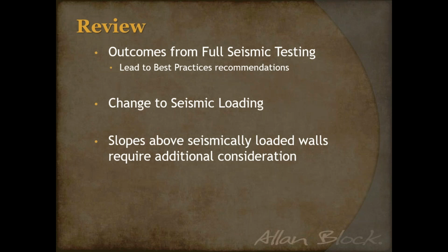Let's be smart about it. Let's raise the height. Let's make sure we reduce the slopes above these walls. If we can do that, now we've got a better solution, as I mentioned before. But you know, this full-scale seismic testing led the way for our industry, and that's 18 years old already. But what we learned is still being applied, that uniform pressure distribution behind, right?